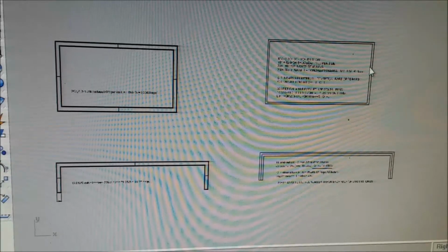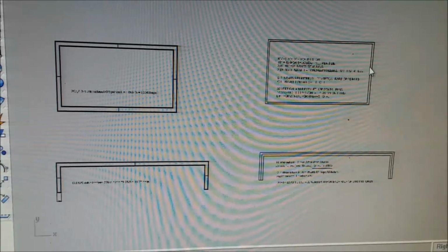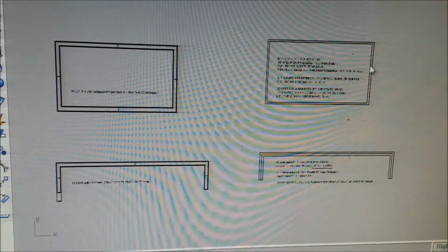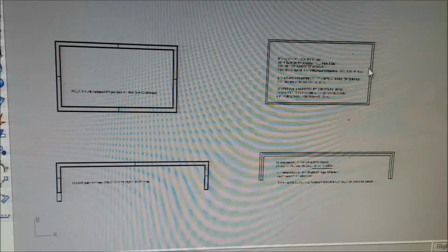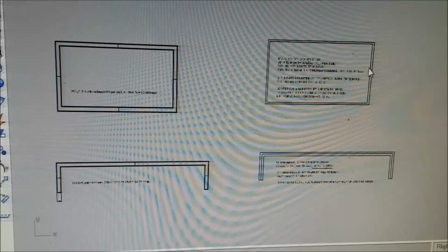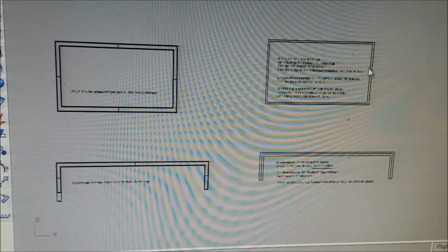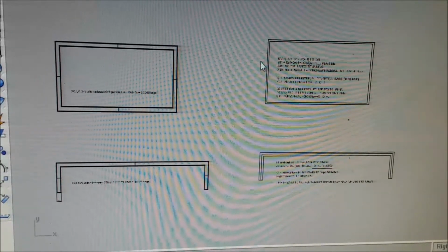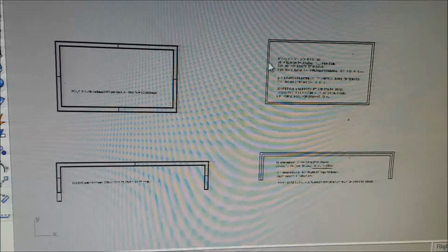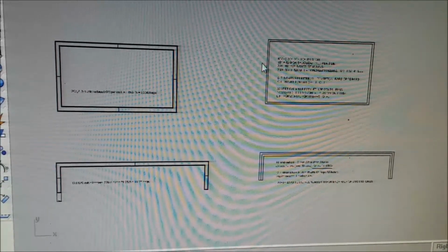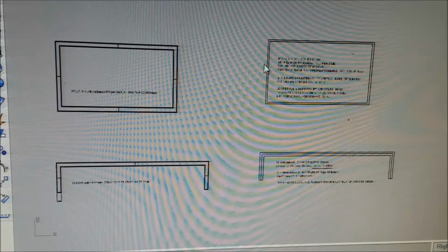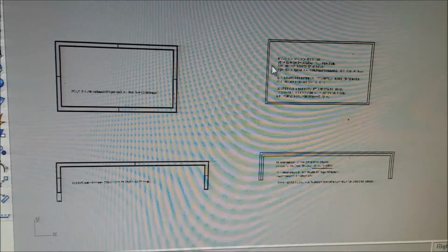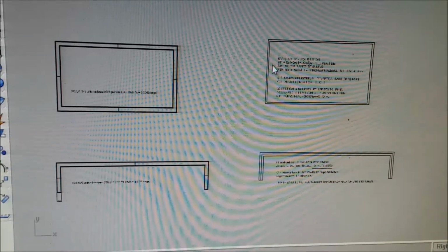For slip forms, it's generally 1 bar more on the 4-foot lift than on the 3-foot-6 lifts. You count how many there are, and you're looking to find places where you've had a drop that's more than 30 inches long, and you find places to put them.